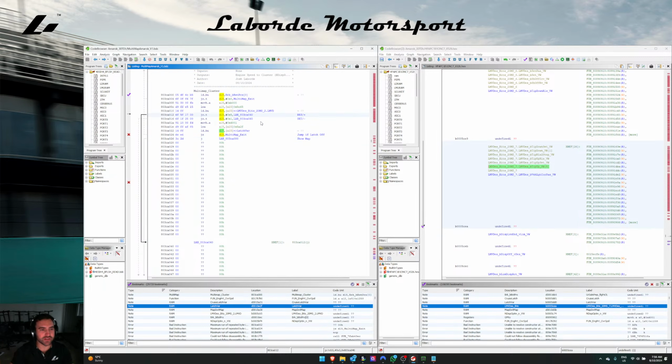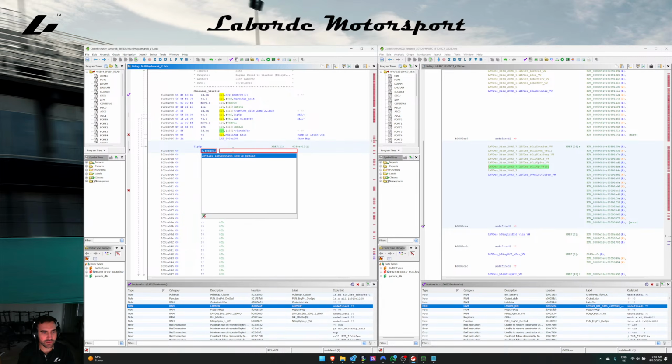Now, what I'm going to do, I'm actually going to jump to here, and I'm going to just call this tip up. And from here, I'm going to check not our latch bar, but our cruise latch bar. This is to make sure that we're not holding the cruise control stalk up, because the raster or the passing time is 20 milliseconds. I doubt very much that you can cycle the cruise control stalk within 20 milliseconds.